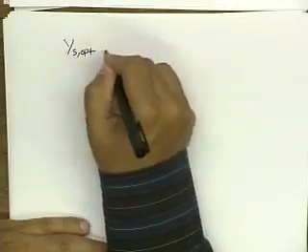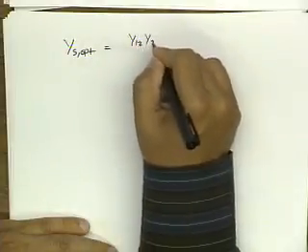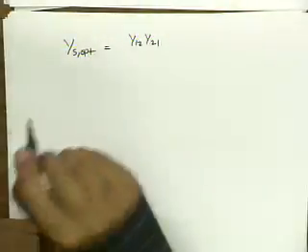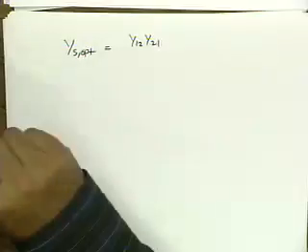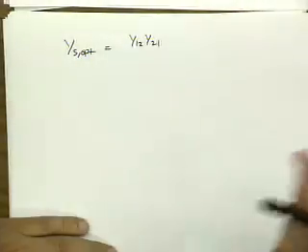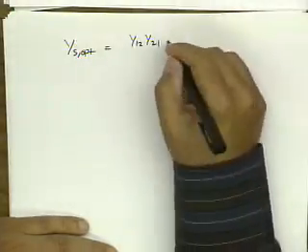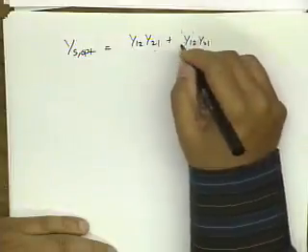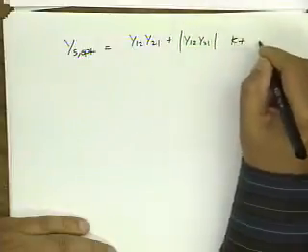For instance, the optimum source: you may ask, how did I get the optimum source? I only calculated the optimum load. Well, you calculate the optimum source by simply saying that Ys star should equal Yout, or Ys should equal Yout star. So you go through the algebra and derive these equations.